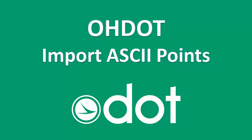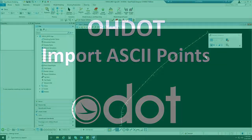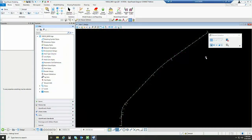In this video, we're going to take a look at the OpenRoads command to import ASCII points from a text file. So I'm going to use some geotechnical data to demonstrate this. What I've done is I've created a geotechnical base map, a BI001 file, and I've referenced in my alignment. I'm going to start by importing my points, and then we're going to demonstrate the process to get a station and offset report for those points.